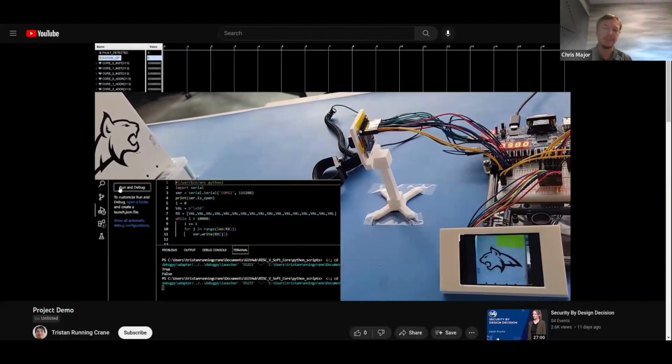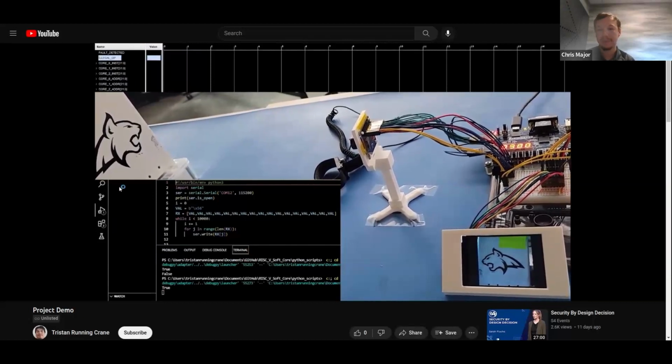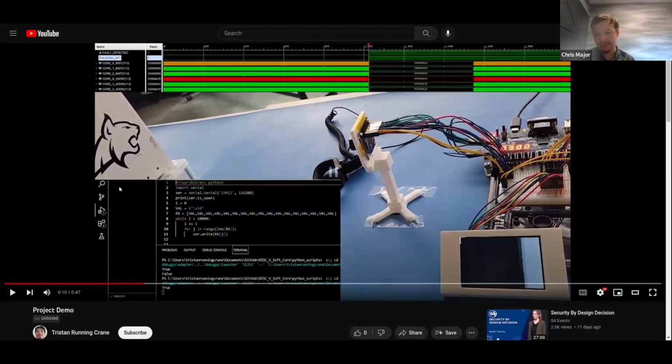And now as you can see here, we have this logic analyzer up top. Now you see how the screen just crashed right there? That corresponds to this little window of time right here. We have an internal logic analyzer in the FPGA that shows all these opcodes firing off on all 4 of the processor cores. And these little gaps up here indicate that a recovery mechanism is watching the cores and saying, okay, everything's fine. They're not reporting any weird opcodes.